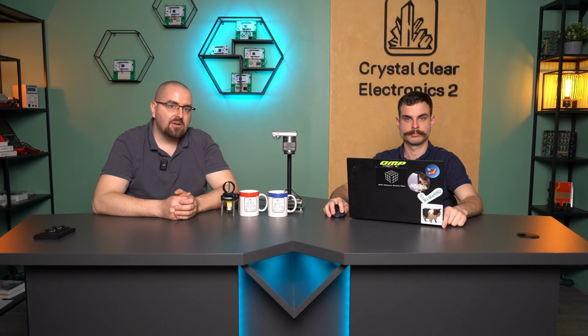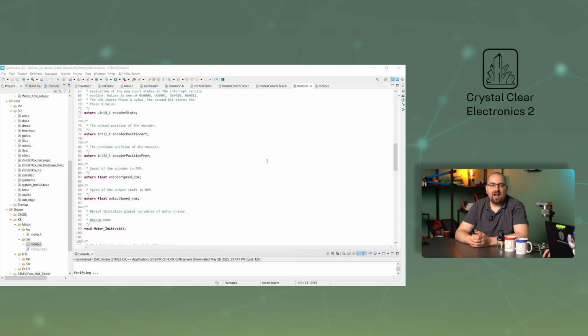Of course, we have used the fact that the encoder can also determine direction thanks to its 2 channels, so if the motor is rotating clockwise, the pulse received will get a positive sign, otherwise we take it into account with a negative sign when monitoring the position. The number of signed pulses given by the encoder is stored in the encoder_position_act variable in the driver program for the motor.